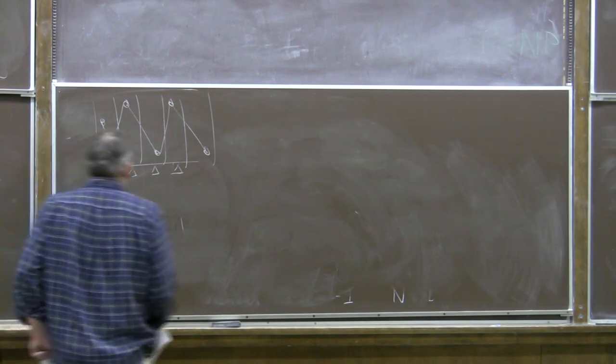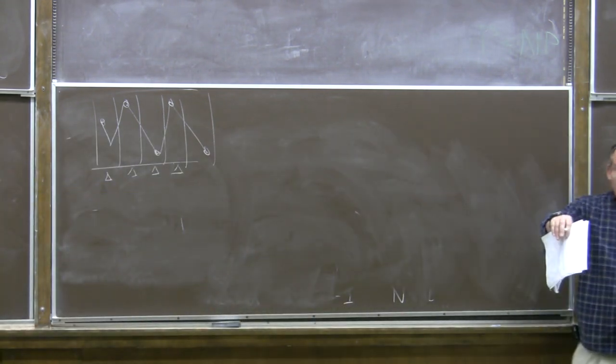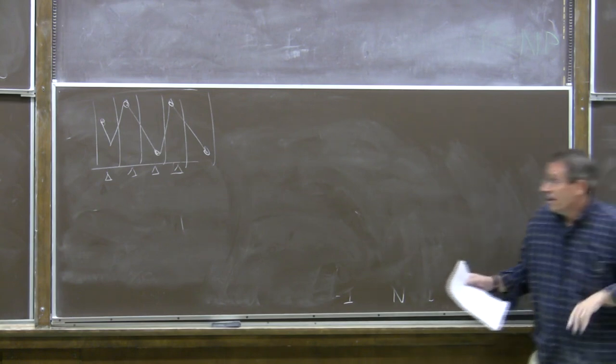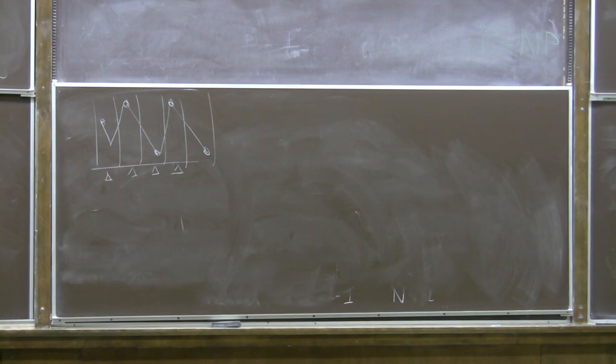So what it means is that if you want to see a voltage signal, you have to average it for a while. Okay? And the Nyquist noise, which has the dimensions of a volt squared per hertz, is what the mean square fluctuations of the voltage look like.